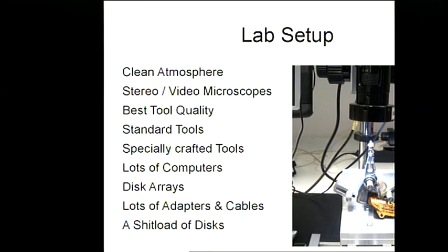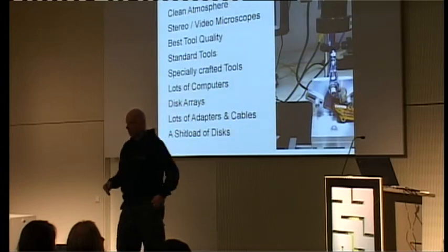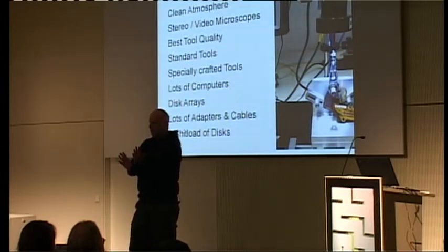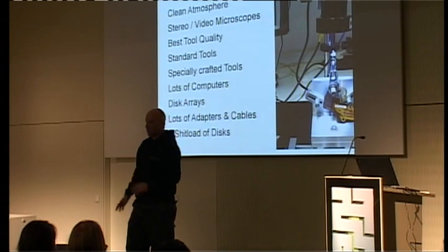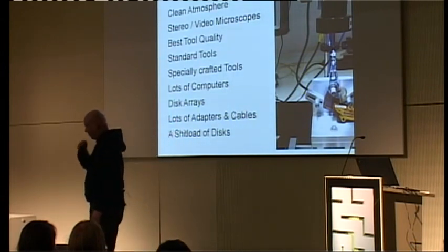Then you need a little bit of microscopy. I will later on show pictures from the microscope, because sometimes alignment of heads is very critical, meaning that you need a video microscope to adjust the heads to their correct position on the head arms.